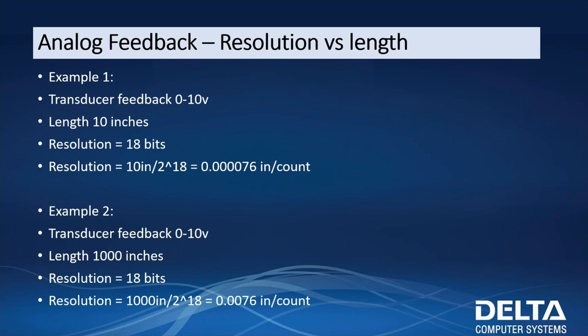Works the same with, say, pressure transducers. If you have a very, very large range on your pressure transducer, and maybe you don't need that large of a range, say you go to 100,000 pounds and you want to be measuring plus and minus 5,000 pounds, and you want to hold within a tenth of a pound, well, maybe you don't want that 100,000 pound pressure transducer.